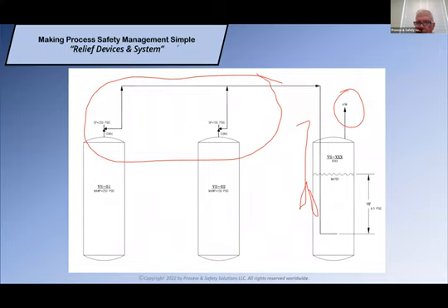In this particular case, I've got 15 foot of water to the bottom of where the material from the reliefs is sparged into the water. So essentially what I've got is 6.5 pounds of back pressure on my system, 6.5 PSIG, especially if I put a constant purge in here to sweep this out, to make sure that I don't have dead legs, et cetera.